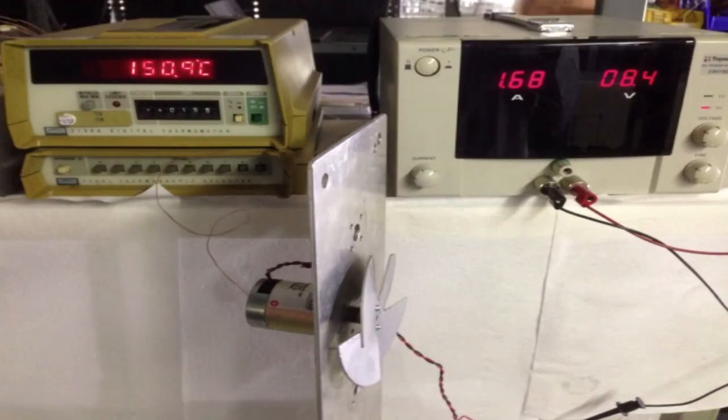Since the motor is now stabilized at a lower temperature, I can increase the load. This will cause the temperature to rise again. Once the winding temperature has stabilized around 150°C, I can see that this motor is now able to draw 52.7% more power and produce 13.5% more torque based on current.